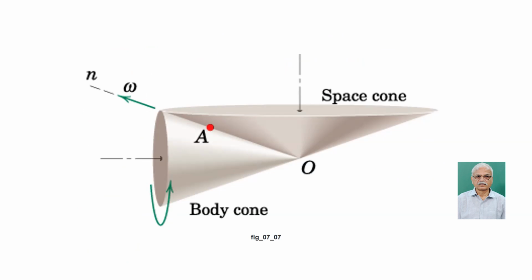We are saying angular velocity here, but if you think of it as a position vector, there is a point P which is traveling along this space cone, on this circle with a center here. Remember, for this example, this omega is traveling on the space cone with an angular velocity of omega 2. The omega itself is omega 1 plus omega 2, but omega is also rotating about the vertical axis with angular velocity omega 2.